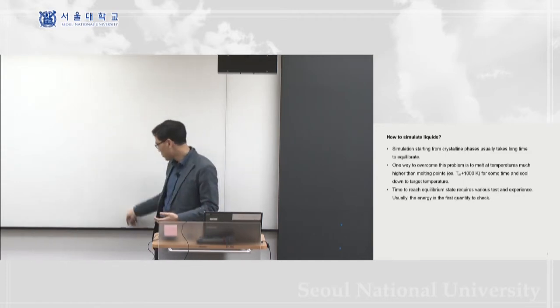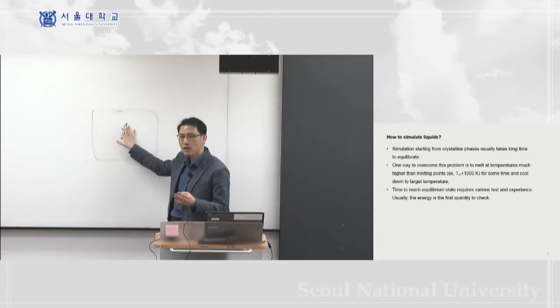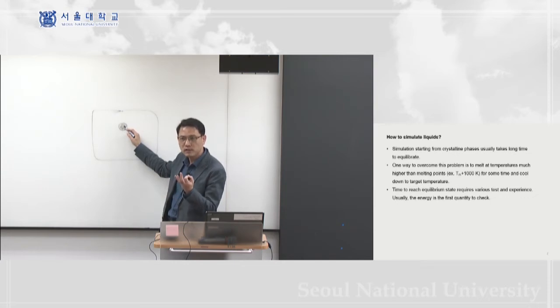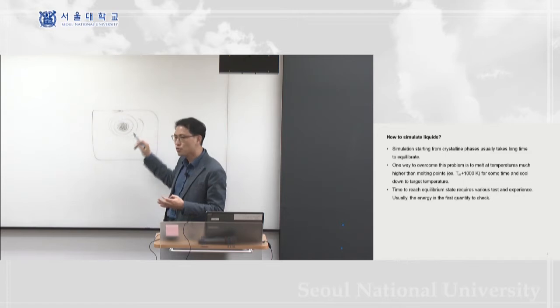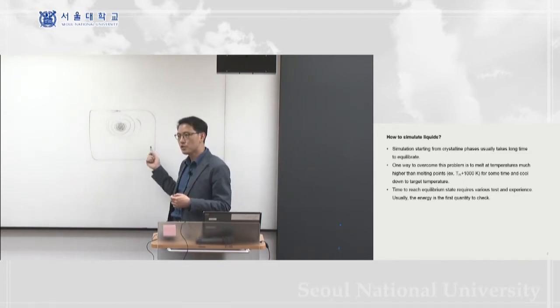In a totally solid material, every atom is ordered, and in some part of the solid you may have some randomly moving atoms, a small nucleated part of the liquid phase, and it will grow. This is the typical picture of the homogeneous nucleation mechanism of the phase transition.